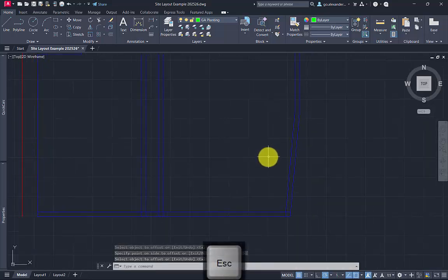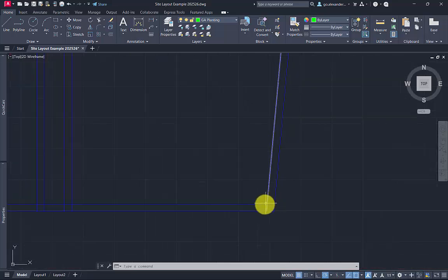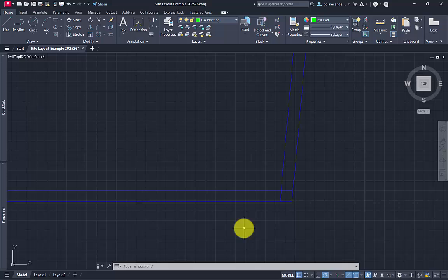And let's also remember that we want to make sure the road has an appropriate radius for footpaths and for vehicles on the road. So I know from doing other work that we can use a fillet tool here.